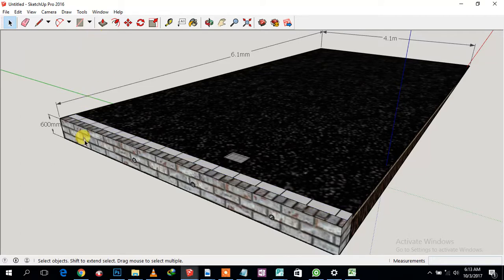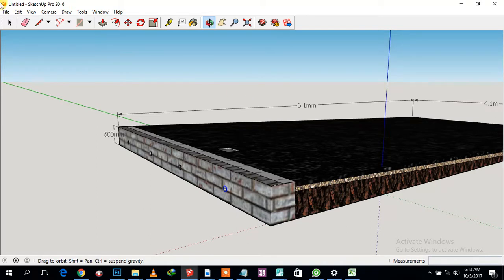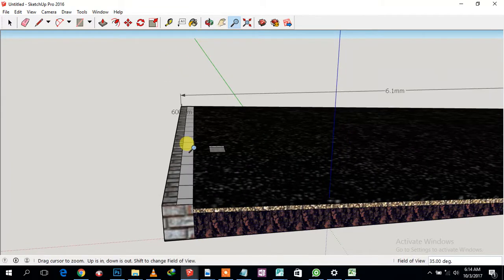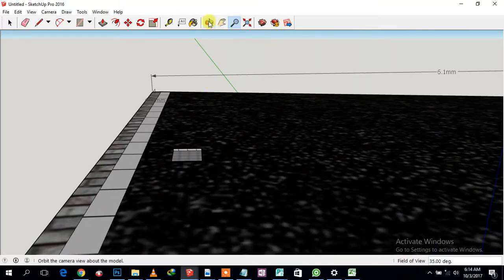And we're probably going to need to put some weep holes to ensure maximum drainage, because there's going to be some water that needs to find a way out just underneath it. And let me bring it closer. So let's say these are the layers. We're going to put all the pieces of old tile, we're going to crush and compact, and then we're going to put fine gravel on top, and then the last layer will be the asphalt or the tar.